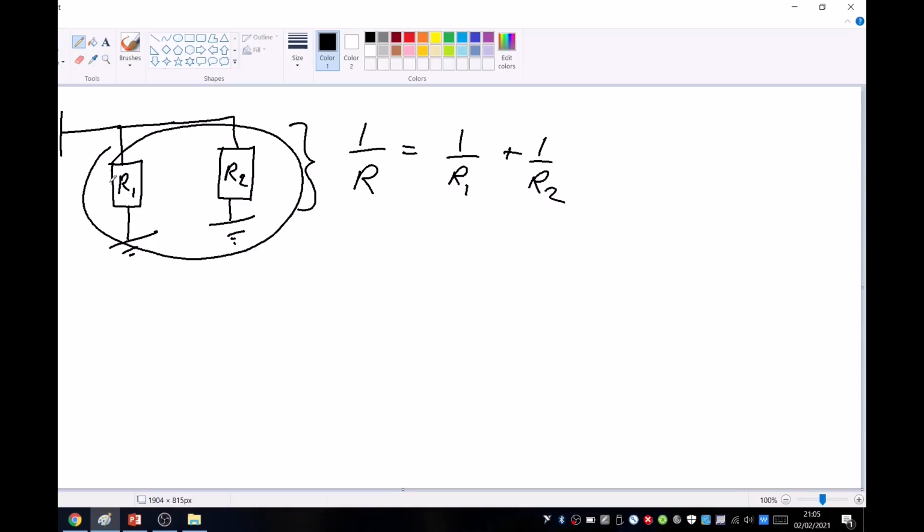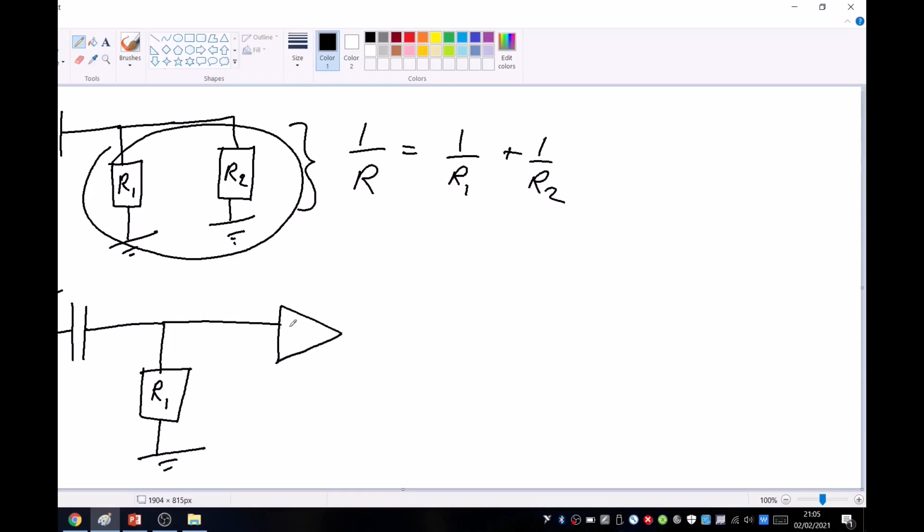And therefore this filter will change its characteristics because its resistance has changed around here. Okay, so when you use passive filters, you have to be careful of the circuits you connect it to. I will just make a point in passing at this point that if we take back to our original filter, we've got C and we've got R1 in there. If we put this circuit in here, which is our op-amp, so we have got an op-amp in now, and then we put a resistor R2 in there, so we've got a capacitance here and a resistor.